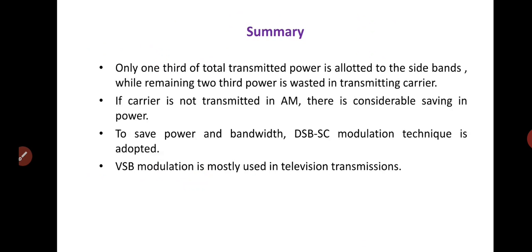The transmission of low frequency components is possible without difficulty, and it possesses good phase characteristics. What are the disadvantages of VSB? Bandwidth required is more when compared to SSB, and the method of demodulation is complex. So let us summarize today's lecture.